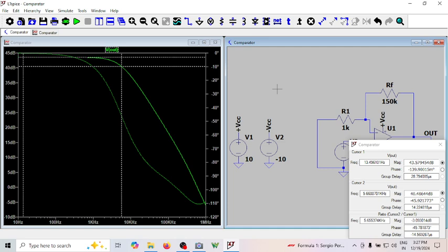So it is 43.57 dBs, which corresponds to a gain of 151, and the bandwidth is 5.66 kilohertz. You can see it is 246. Gain bandwidth product has reduced a lot, so it's not remaining constant. This is a concern now. Gain bandwidth product has reduced.